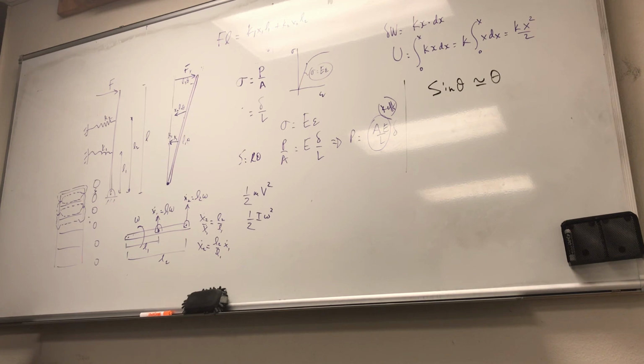Now, what kind of dampings do we typically have? Well, it says here it is difficult to determine the causes of damping in practical systems, as damping is modeled as one or more of the following types. In fact, 3 of these. The first one is really the most common one. It's viscous damping. That's the one that we like because it is proportional to the velocity. It is great. But there is also what we call Coulomb damping.